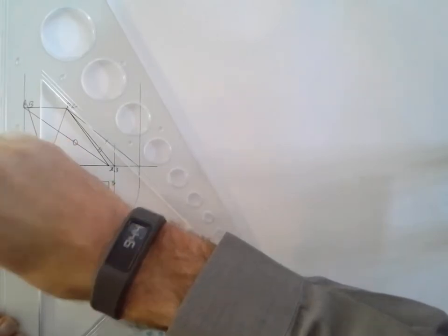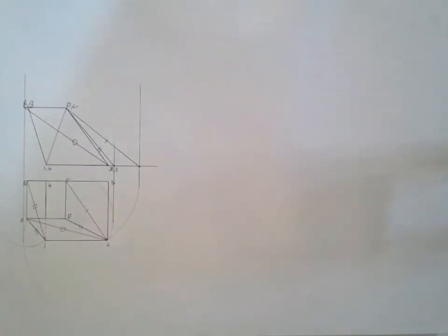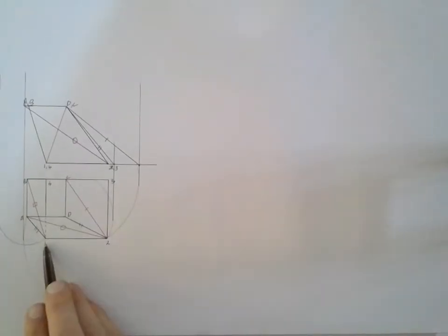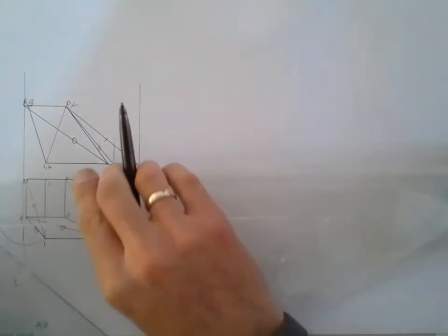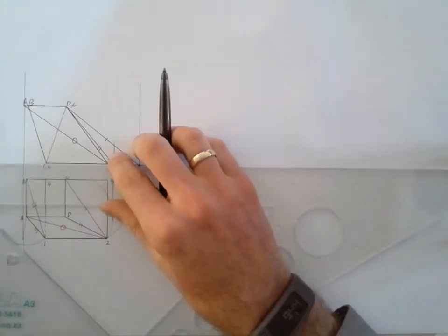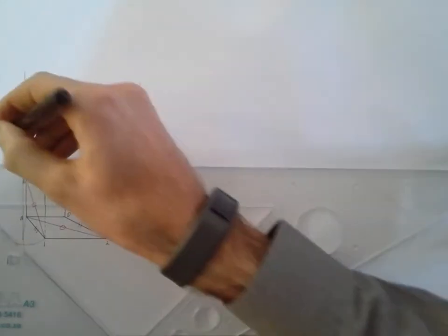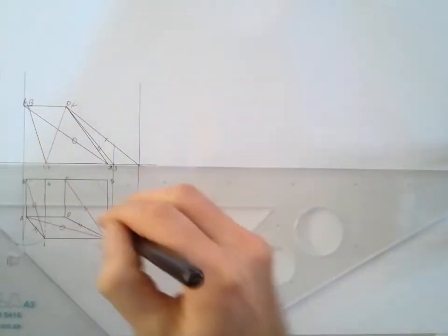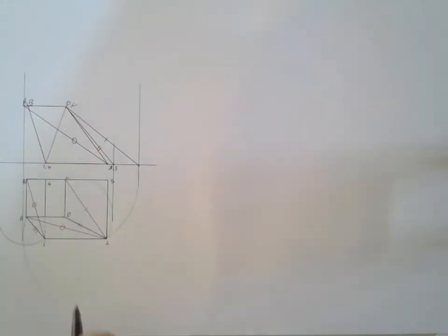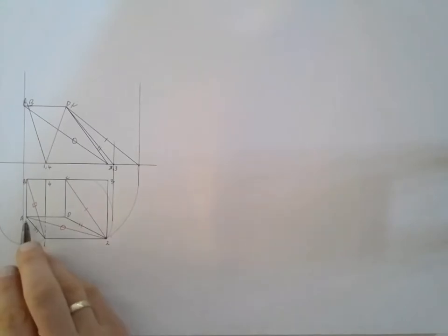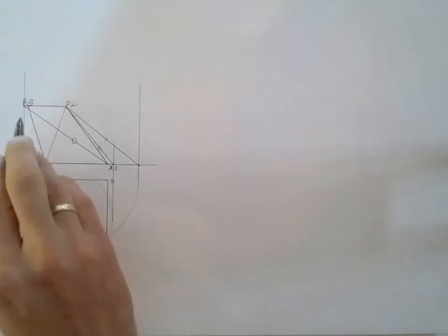And now I've changed again. I've now projected a base point again, point 1. So because I've projected a base point, I've got to join that up to the baseline of my front view. So I'm going to extend that, so that's the point I'm working from. I placed my compass point on point A in the top view, so I have to join that point to point A in my front view.